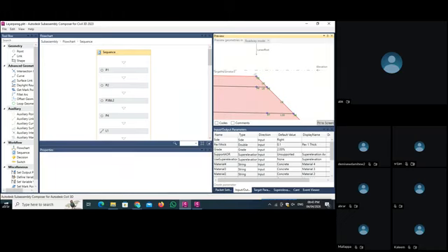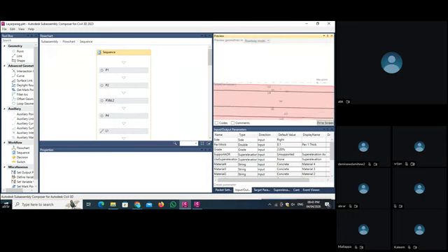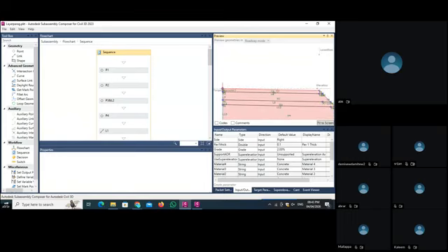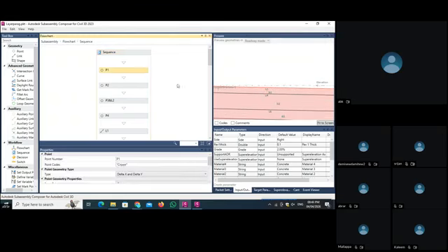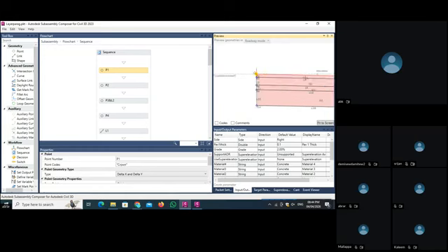So the points that we set first, then this is the link. The link is created between 2 points. So if I want to join these 2 points, I have to create a link. And the shape is given here in the center. Once this closed boundary is created for the first pave road, we give the shape here. As you select the P1 point, here the P1 point is selected in the preview mode. And in properties mode, we give the point code as a name, as a crown.